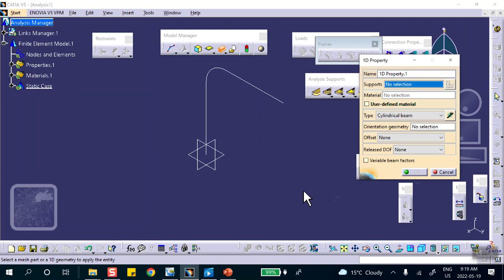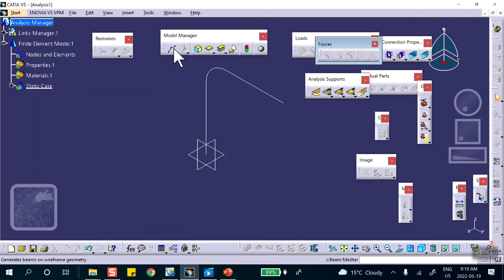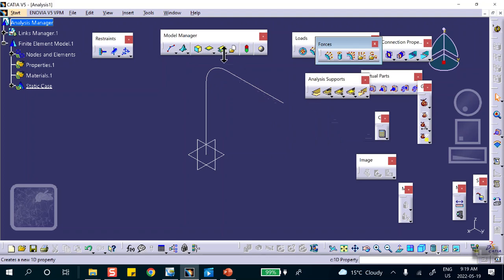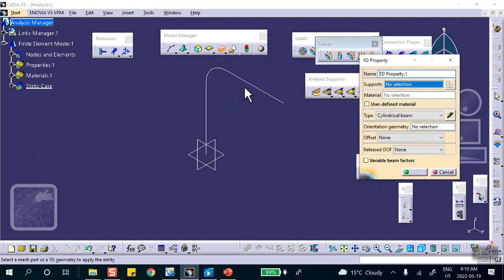It doesn't work. It's not even taking it. Can you guess what it is? Why? I did join it. I think I joined it. I did. But why is it not taking there? Because I haven't even meshed it. Okay, so cancel this. Mesh. Right? You have to mesh it first. There we are. Say okay. Now, cross section. I can select it. 0.25. Remember 0.25? There's 4 of them now because there are 4 segments. Okay.